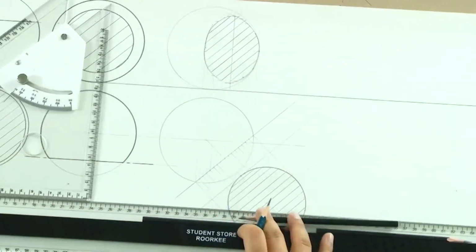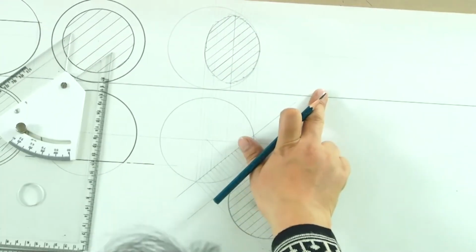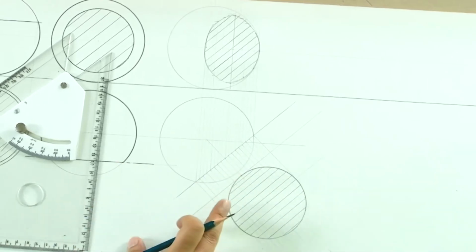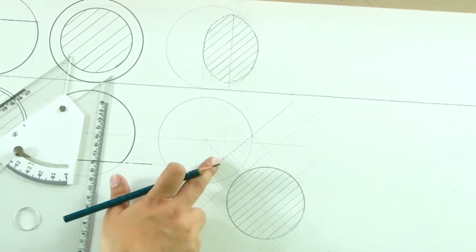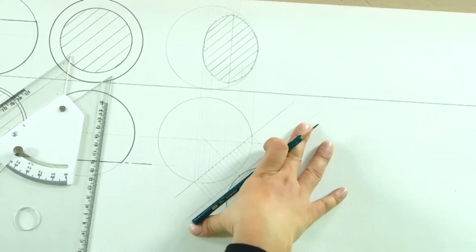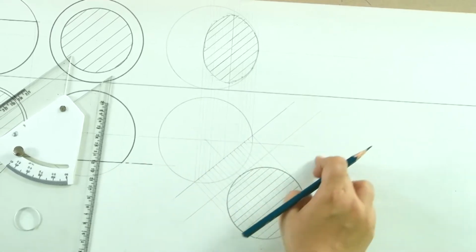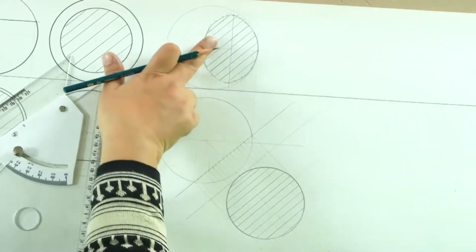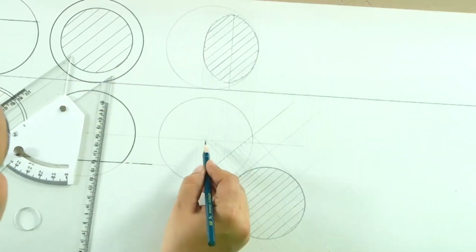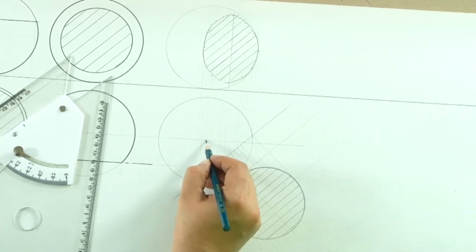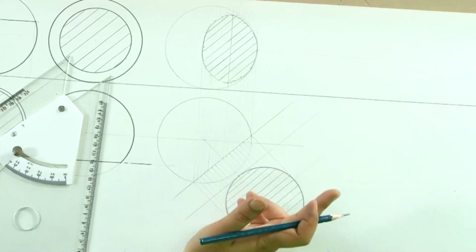In this case, this is a plane which is inclined to VP and it is perpendicular to HP. So we are seeing the true shape of the section here, and instead of taking the distance, because we didn't know what is the distance of this point from XY, we just took a hypothetical line XY. But we surely know where the center line is going to be, which is there, and then when we cut it, this is how it is going to be. Now why would the center line come here? Because the center of this circle will always lie on a line joining the center of the sphere. That is the rule, we always know it.